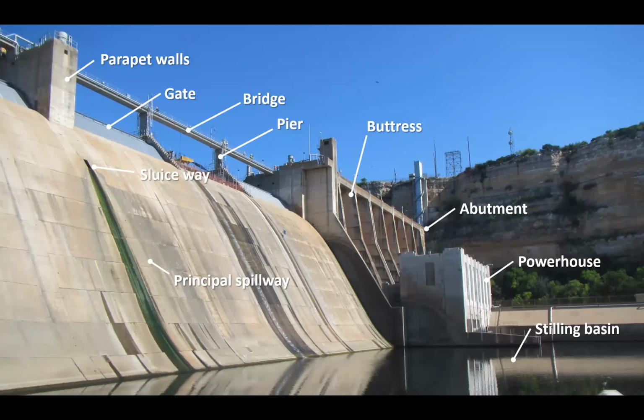And this dam is not solid. It is actually hollow inside. It has buttresses as part of its support. And dams, by way of function, are not intended to be overtopped. That is, they have mechanisms in place. They have gates up at the top to help release water. But their primary use is not to overtop them. That is, you want to direct the water in a controlled fashion down to a powerhouse or other methods. Have a controlled release of water. You don't want to be in a situation where they're being overtopped.